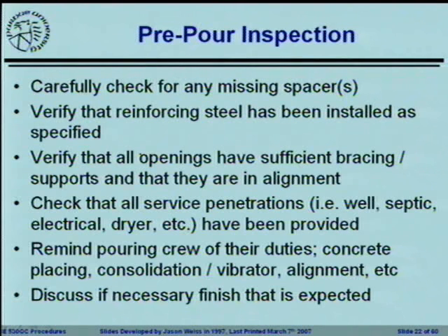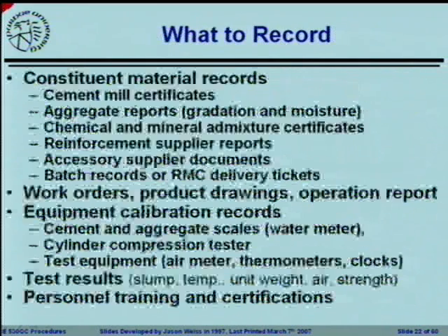Service penetrations. Here, if you've got anything that's going through a poured concrete wall, through a poured concrete floor, you can save quite a bit by making sure it's installed in the correct spot from the beginning. Reminding everybody of their jobs, and then discussing the finishes.